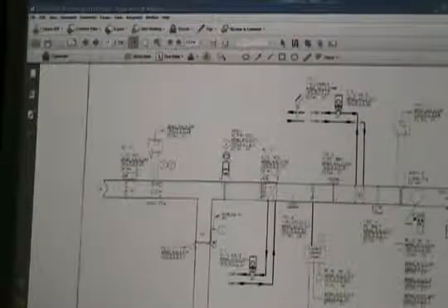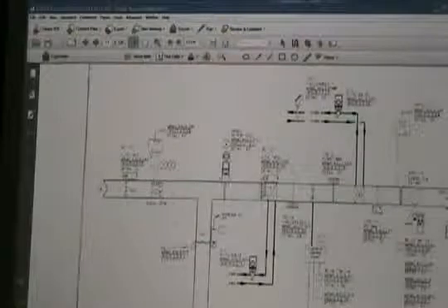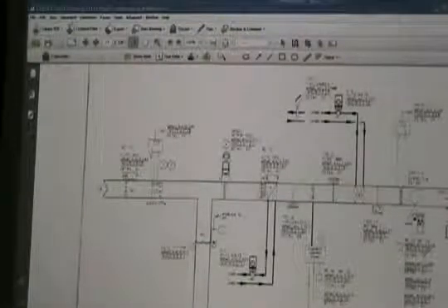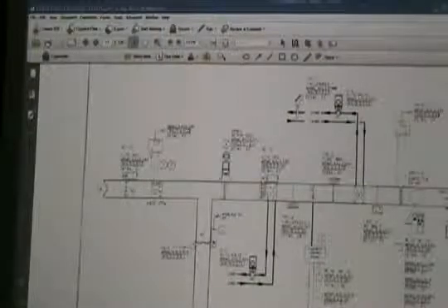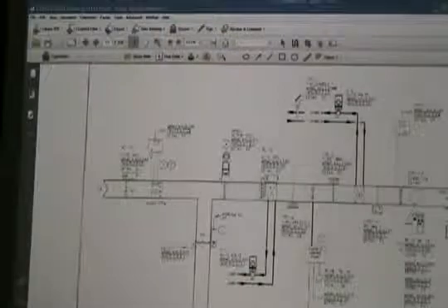High humidity. I think that's high humidity, 95%. There it is, it's set right there. So he's got that humidity sensor set at 95%, which is a good thing, because it's upstream from the cooling coil. Downstream of the cooling coil will be 100% humidity most of the time, because it's just saturated airflow.